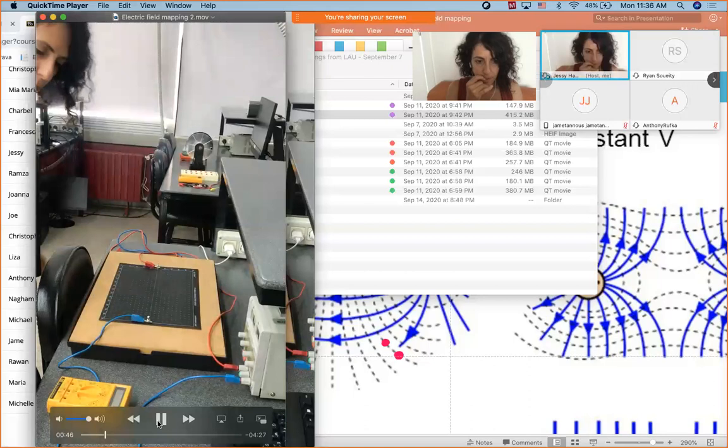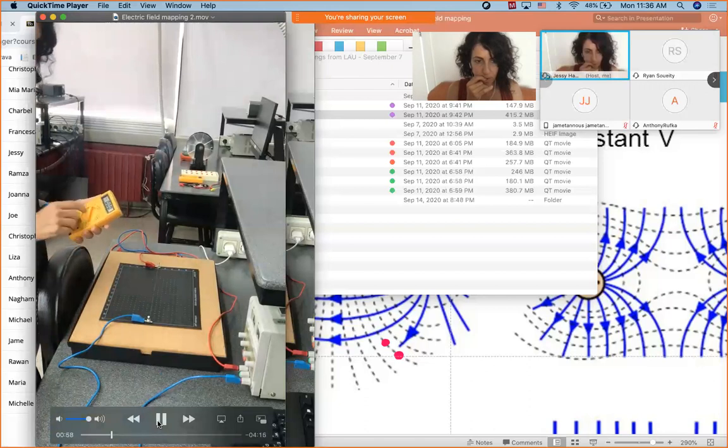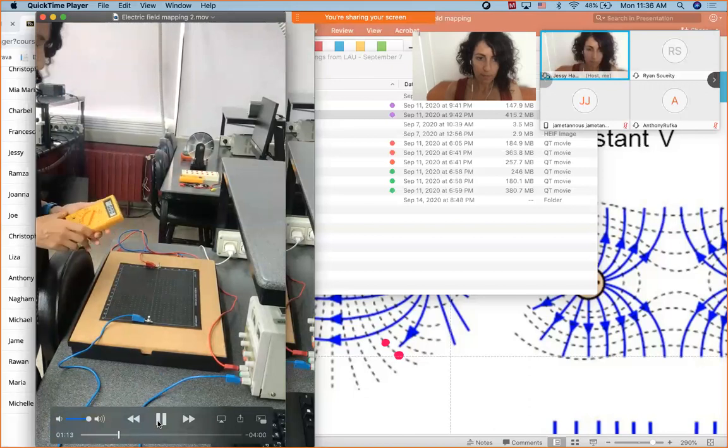I will use my voltmeter on the scale 20 volts because 20 volts will give me 2 decimals. I will not be measuring voltages more than 2 volts though, so I can simply use 2 volts as well. But 3 decimals for me is a lot of precision, and I don't need this, knowing that the experiment is not super precise. So a scale of 20 volts or measurements of 2 decimals are enough.